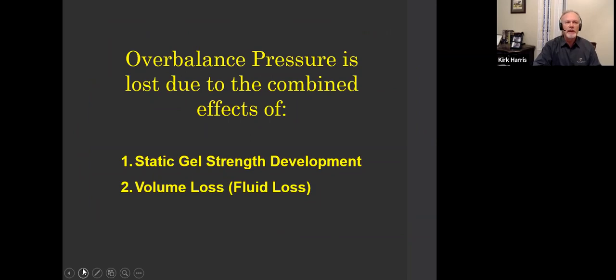If I were concerned about it, as soon as I dehydrated the first part of my cement, I build filter cake. It's not that important. As a matter of fact, when it comes to dehydrating cement, almost all the time when we get a flash set or we're worried about dehydrating, it's due to formation coming in or solids packing off. It's not due to the lack of fluid loss, in my opinion. But I am interested in having low fluid loss, especially that I keep the overbalanced pressure in the well after I have placed the cement.